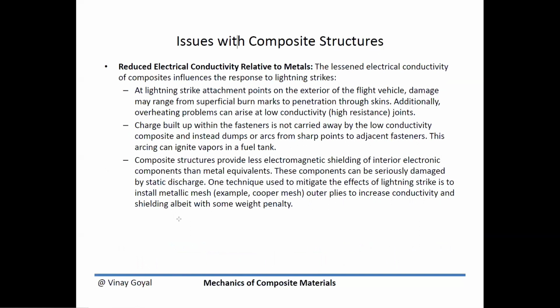Reduce electrical conductivity relative to metals. The lessened electrical conductivity of composites can influence the response to lightning strike. I already talked about it from the heat perspective, but at lightning strike attachment points to the exterior of the vehicle, damage may range from a superficial burn mark to some penetration into the skin.